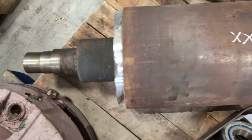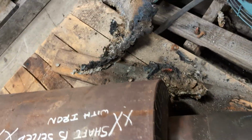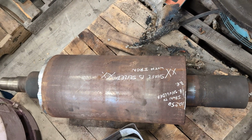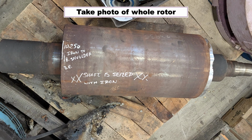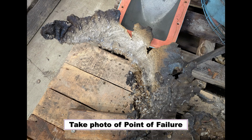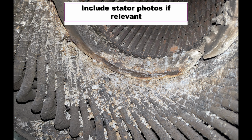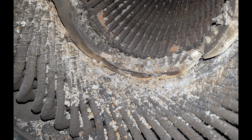I can see on this rotor, we've got a little bit of melted end rings. This rotor has got a problem with high residual magnetism. I want to take some photographs. Now that is useful information when we do the combination of all the results together. We will do analysis and see which kind of failures correlate to rotors with problems.